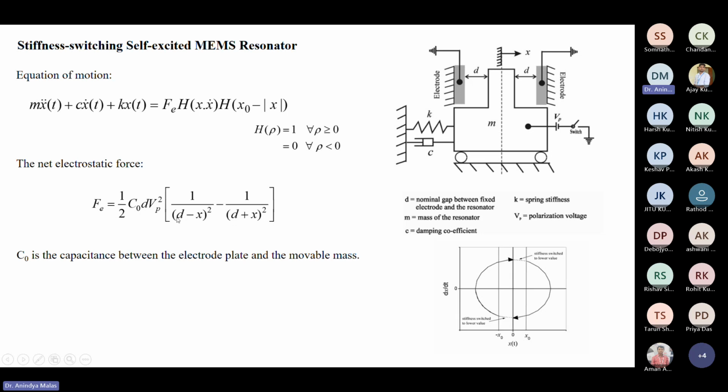So this force function is a function of the state of the system, and that is the reason why it is called a self-excitation mechanism. Though we are providing it through feedback, and we need some power and some controller like that, as the forcing function is not external but internal, we say it is a self-excitation mechanism. So with a constant voltage, we can generate this self-excitation.